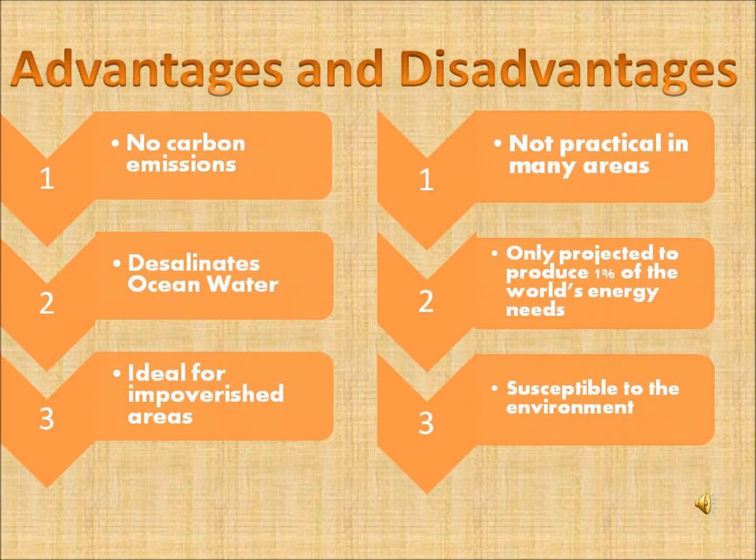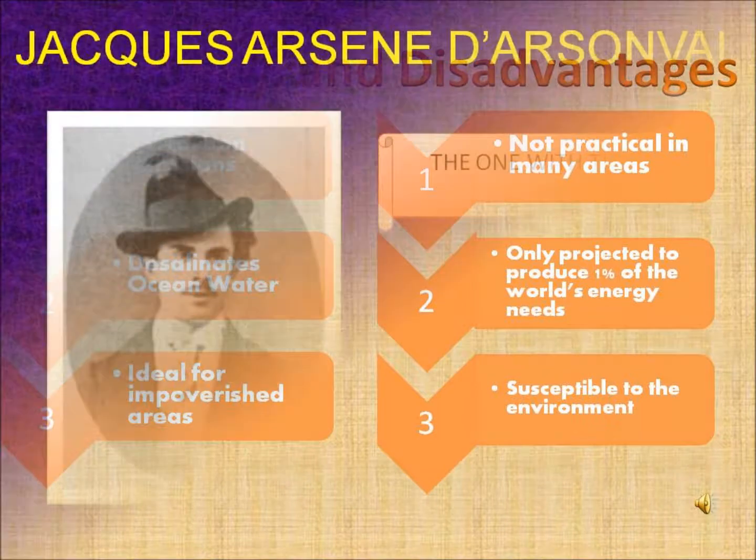Here are some advantages and disadvantages of the OTEC system. 1. As one can see, OTEC is a renewable energy, which is always a positive when combating climate change. And 2. The fresh water that is obtained from the plant could be used for refrigeration, coolant, and irrigation, which could prove to be useful in tropical areas. However, OTEC cannot be used at large scales, similar to how fossil fuels such as coal and natural gas are used today. These plants can only be built in select areas of the world and cannot be heavily relied on because of the rough environment the ocean poses. Therefore, OTEC can only help offset and not completely replace current energy sources and other renewables which have the potential to be used at large scales.